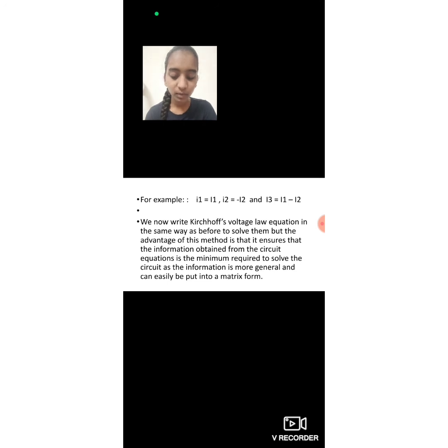The essential meshes are 1, 2 and 3. A mesh current is a current that loops around the essential mesh, and the equations are solved in terms of them. A mesh current may not correspond to any physically flowing current, but the physical currents are easily found from them. It is usual practice to have all the mesh current loops in the same direction. This helps prevent errors when writing out the equations. The convention is to have all the mesh currents looping in a clockwise direction.